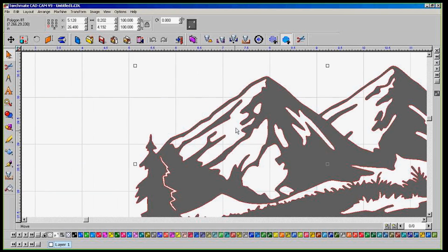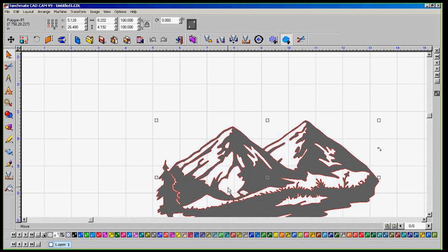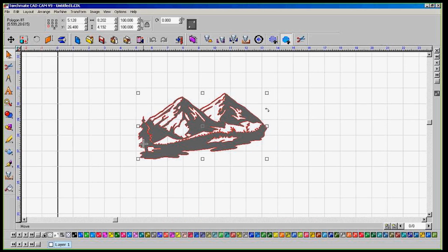Now, as we can see, here is the piece of Clipart that was brought in with the closed shapes and remove duplicates. We noticed as this was coming in that it immediately did an arrange and make path. And the reason why I know that it did that is because the inside features have dropped out, and it just shows us the actual mountains and the way that this thing is set up right now.